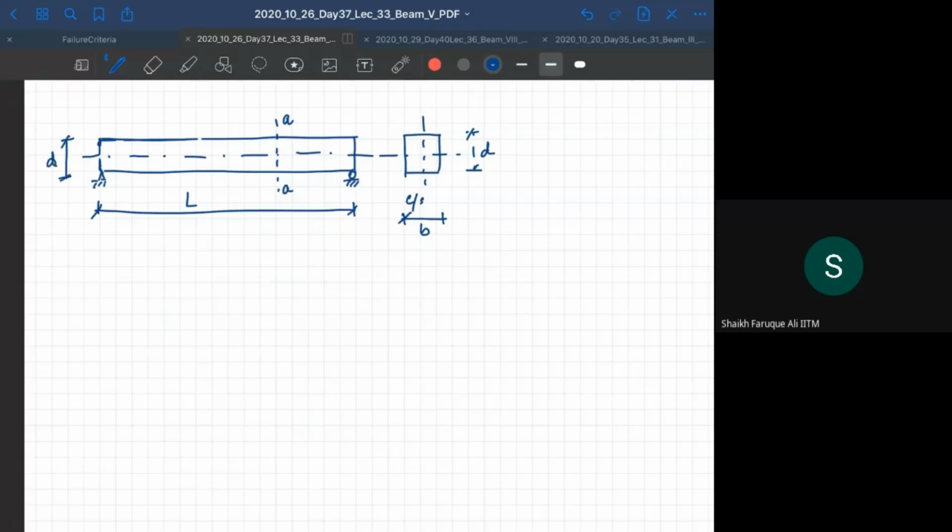Okay, clear. So that actually is a cross section. That's not part of the length of the beam. It is a cross section of the beam. And that is actually here, this one that is drawn here. Now, this is how you draw. So you show all the dimensions.